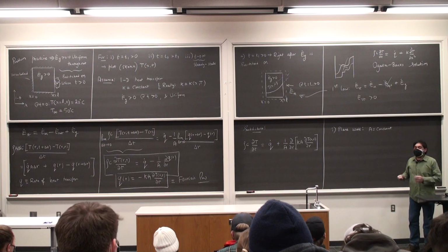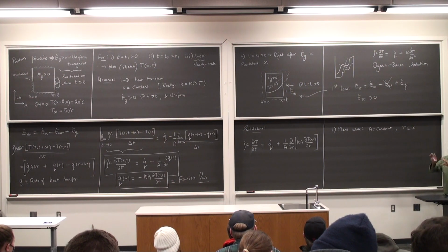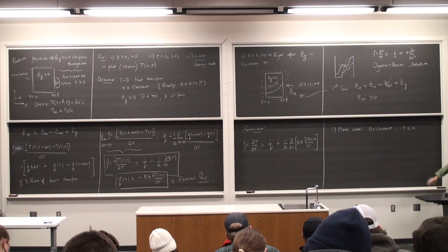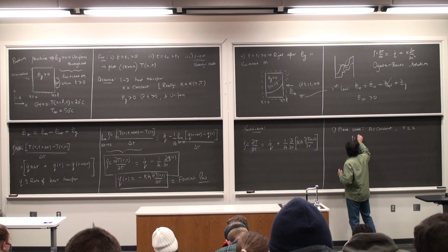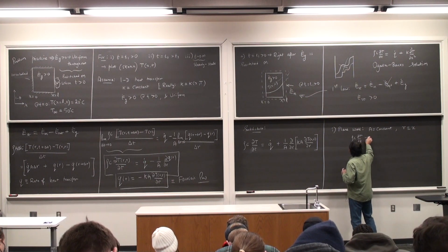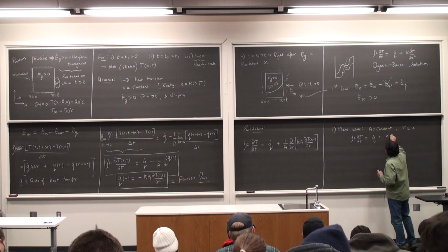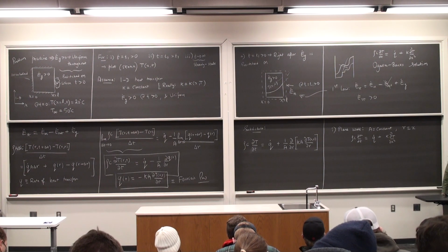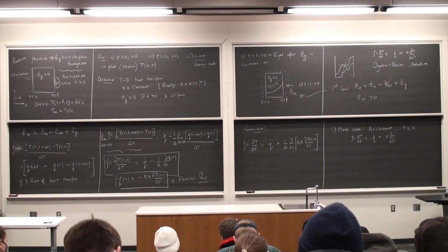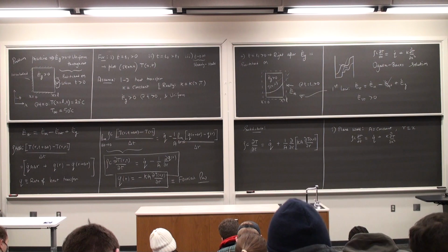And if I say that R is the same as X, usually for one-dimensional plane wall situations we assume X as the variable of interest, you will end up with your regular equation: rho C dT by dt is Q dot plus K times d square T by dx square. All I'm doing is substituting R as equal to X. This is for a plane wall.